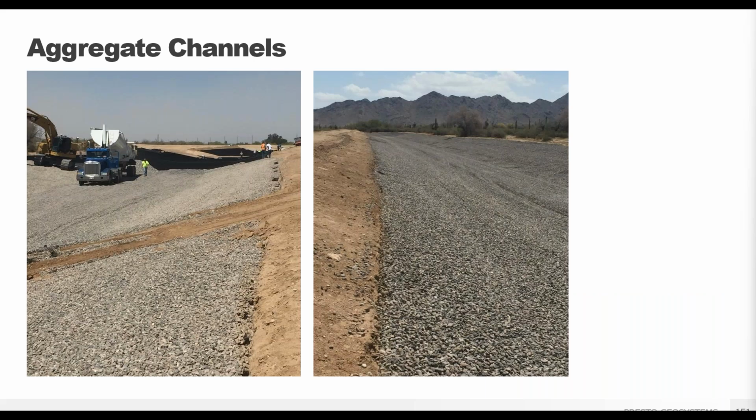The infill was waste rock from a nearby quarry and not the greatest quality, but that's okay. When using GeoWeb, the rock does not have any requirements other than size and that it be angular, so money can be saved on material and hauling costs. The only infill material we recommend avoiding is river rock or rounded rock, since it does not lock up as well and will be scoured away over time.